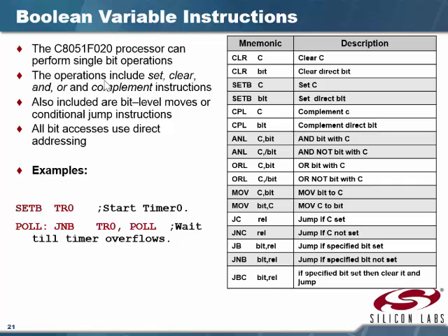That's where that P program status word is. Now, you asked me what it was, I couldn't remember. Now I just popped it off without thinking about it. That the carry flag is in the program status word right there. So we clear a bit. I think in Blinky we cleared P1.1, for example. That's a bit. We can set a bit. We set the carry flag, or we can set a bit. So we can set P1.1, which turns off the LED right there.